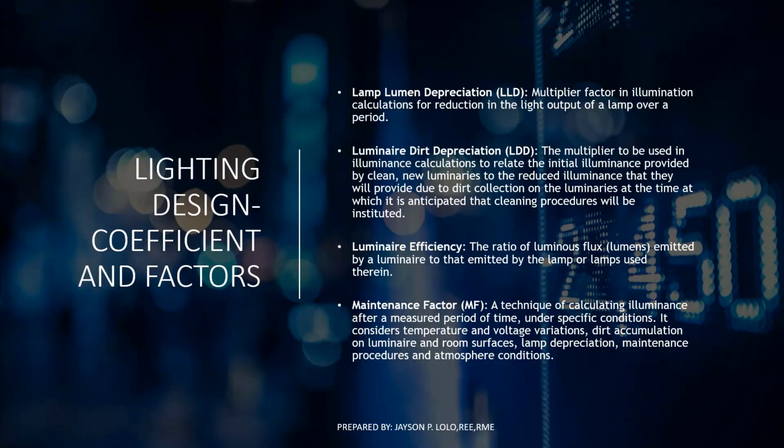Next are the lighting design coefficient factors. We also consider the LLD, the LDD (luminaire dirt depreciation), the luminaire efficiency, and the maintenance factor. The LLF is a factor used in calculating illuminance after a given period of time and under given conditions. It considers temperature and voltage variations, and dirt accumulation on luminaires and room surfaces.